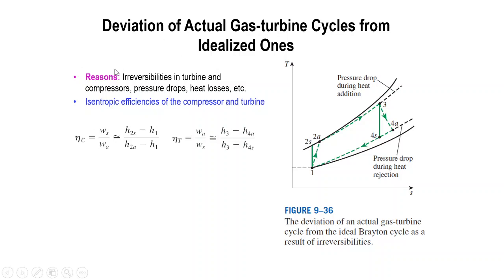For the isentropic compressor and turbine, we have this equation. We have state 2s and 2; 2 is the actual one, and 2s is the isentropic condition. From the enthalpy at H2a, the actual, we can get the efficiency for the compressor. H2s is the shorter one, and the actual is the longer one. So it is H2s minus enthalpy 1, divided by enthalpy actual minus enthalpy 1.